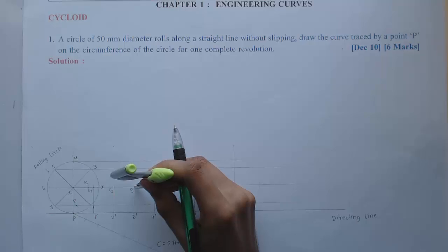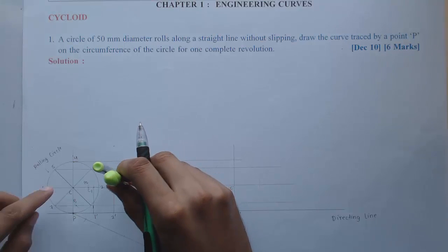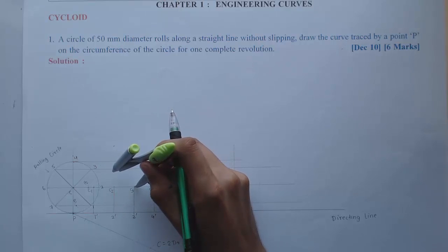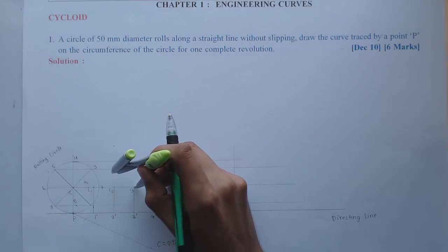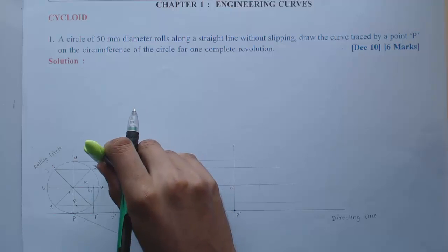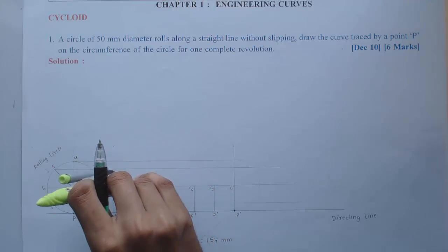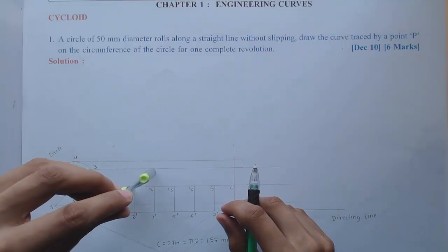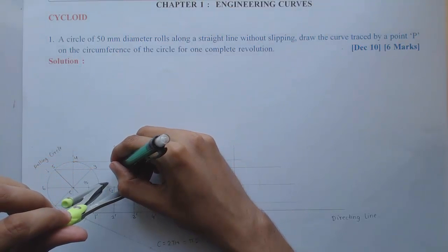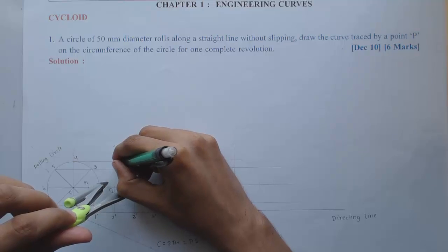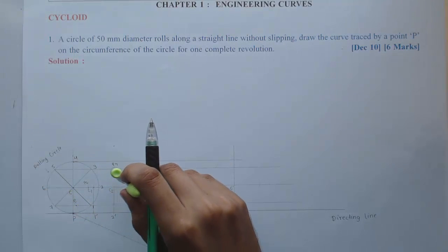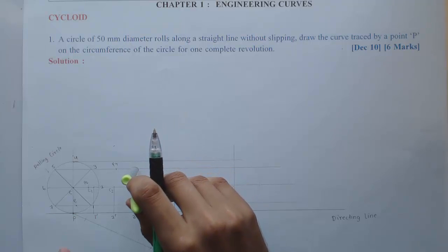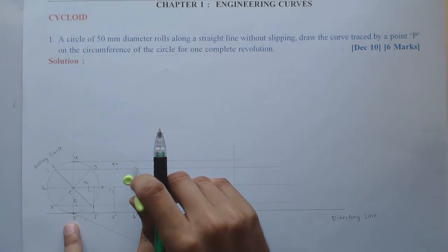Similarly, for P3, we need to decide from division 3, on the horizontal line passing through 3 with center C3, I need to cut an arc. Again, we need to decide which arc, this or the other side. Obviously, it will be on this side. So it is P3. When we have reached C4, that means we have reached half of the distance of the circumference.